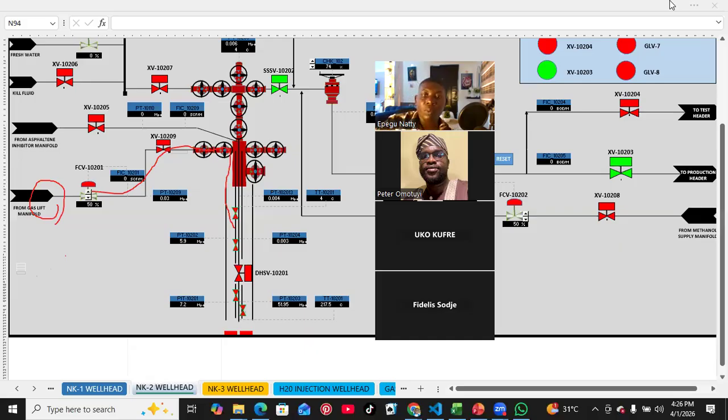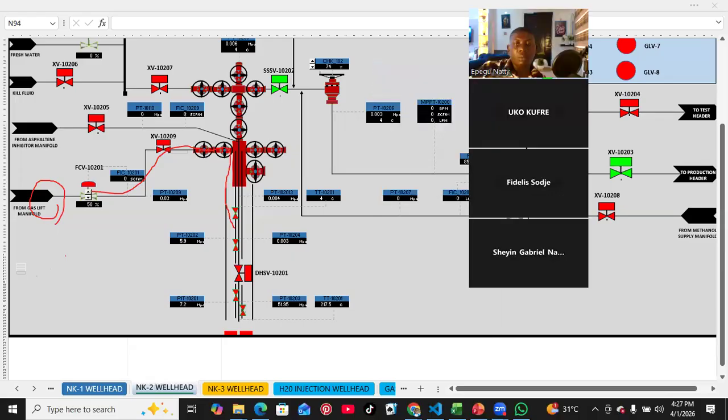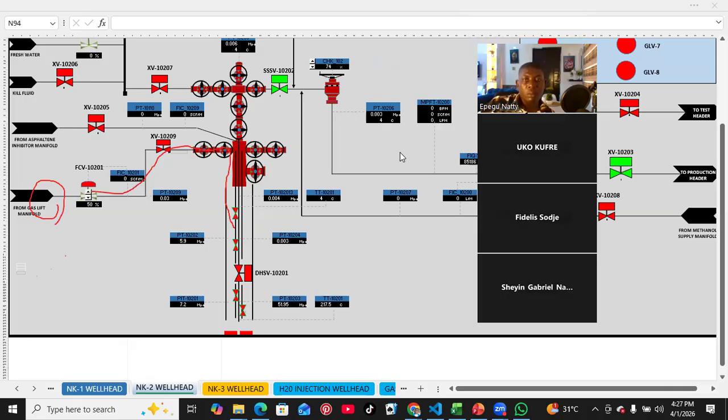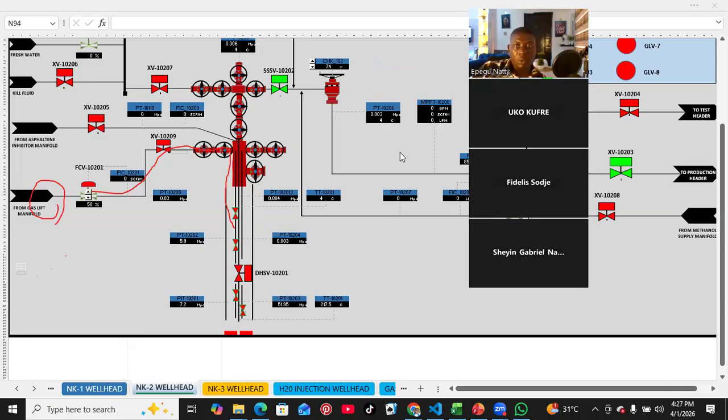Sir, to shed more light on the water injection: the other well you drill, when setting in your injection tubing, it will be at the water zone. In the reservoir, we have the gas, the oil, and the water. So you will not set your water injection tubing on either the gas or crude zone. You will set it at the water zone layer so that it will be able to boost the production of the crude oil. That's the aim. That's just what I want to explain. Thank you. All right. Thank you for that addition.